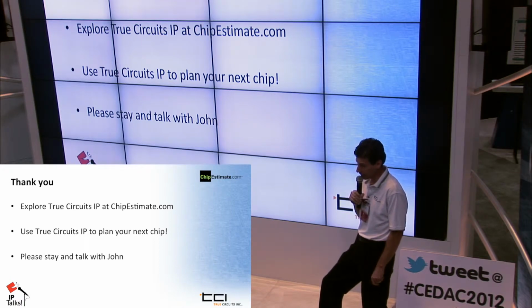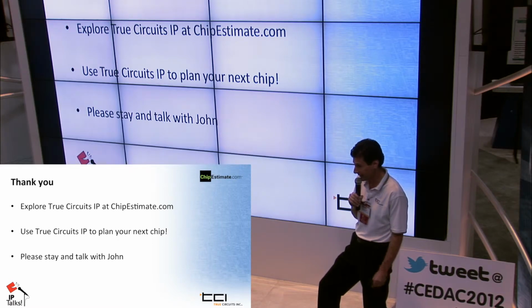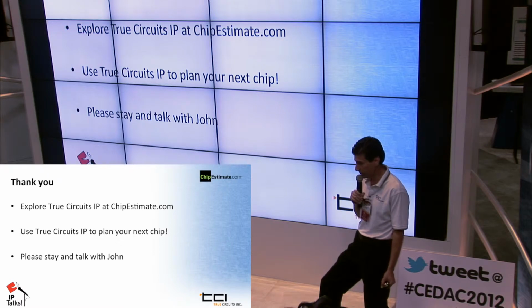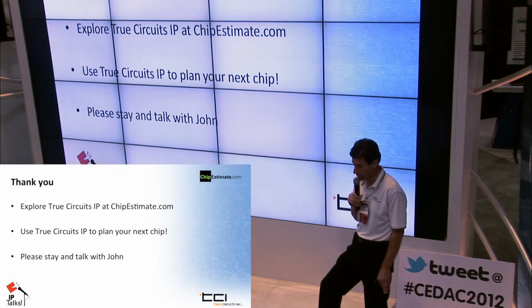Pre-silicon verification we do with our automated characterization environment. We run thousands of simulations on the designs. We have a very large computer farm that we run. We actually use our own version of SPICE, so we're not limited in any way. We will run thousands of closed-loop simulations, millions of open-loop simulations, to verify that the circuits will work well under all conditions.